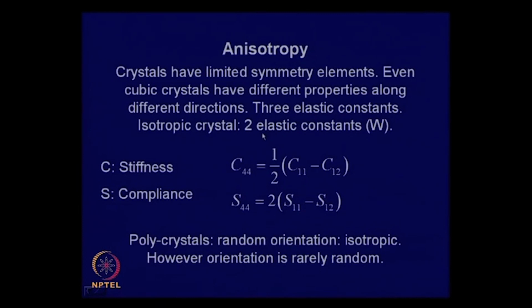However, if you look at the elastic constants of tungsten, this is an ideal isotropic material. Even a single crystal of tungsten will satisfy this type of relationship. So, one point that you can infer is that polycrystals are made up of a large number of crystals. In a fine grain you will have a very large number of crystals per unit volume, so the finer the grain, the more likely the property will be isotropic.